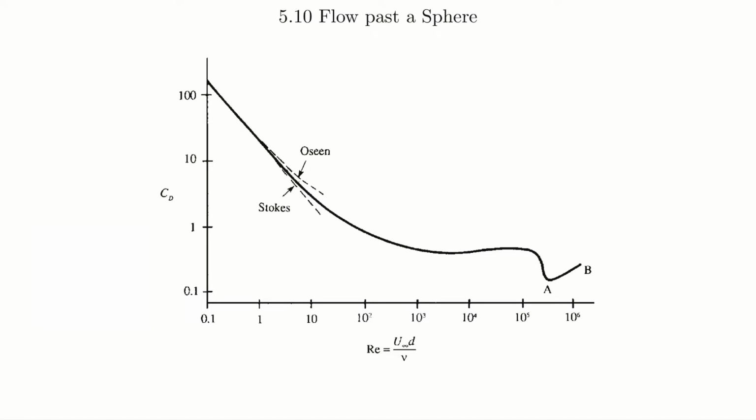a donut-shaped ring. And then this ring eddy will oscillate, and some of it breaks off periodically in the form of a distorted vortex for Reynolds numbers above 130. The behavior of the boundary layer around a sphere is also really similar to a circular cylinder. In this plot, we see the transition to turbulence right here, which is roughly at Reynolds critical, approximately 5 times 10 to the 5. And so we see this very dramatic drop in our drag coefficient that's plotted here.